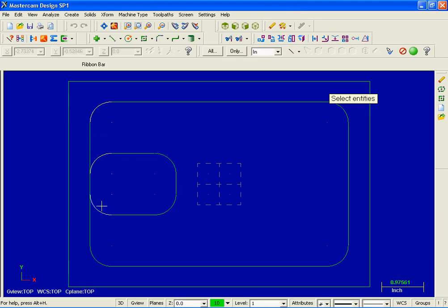this one needs to be deleted, and right down the bottom I'm going to get rid of this one as well. Now one last thing, I'm going to delete this vertical line on that last rectangle that we created. Now I'm done. I'm going to move over and click on End Selection. Now our next operation is to do some trimming.